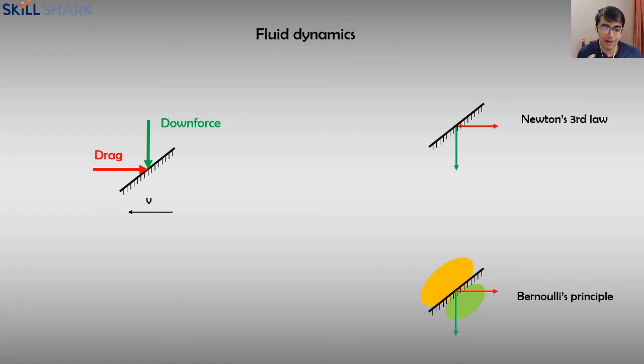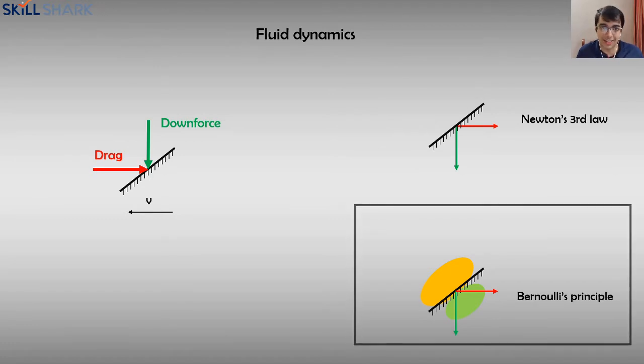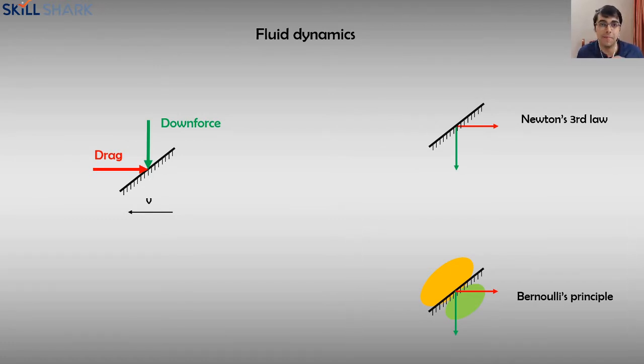So of course the air above the plate slows down, and that becomes a high static pressure zone. And below the plate, it's sort of a pocket. In this case, there isn't much flow directly underneath that plate, so it becomes a low pressure zone because there isn't really any air per se present over there. And that causes a pressure differential, and it presses the plate downwards in that direction that I've shown you, and then it again gets resolved.